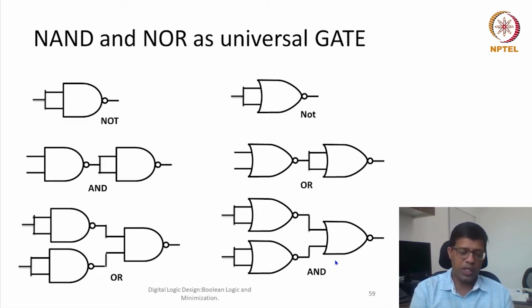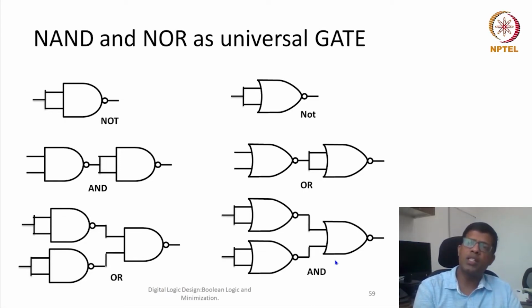what they did was create some sort of programmable hardware by designing a sea of NAND gates. A sea of NAND gates means they created a chip which has thousands of NAND gates, and because fabrication of a chip was always a costly and complicated affair, once they had fabricated these NAND gates, they then used them to construct any sort of design, whatever they wanted to configure.